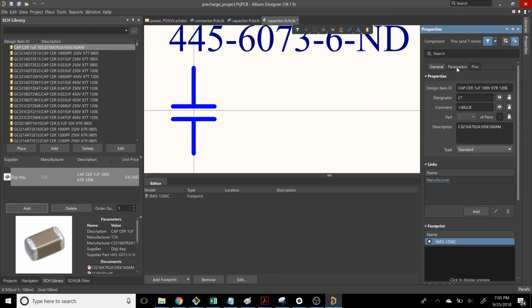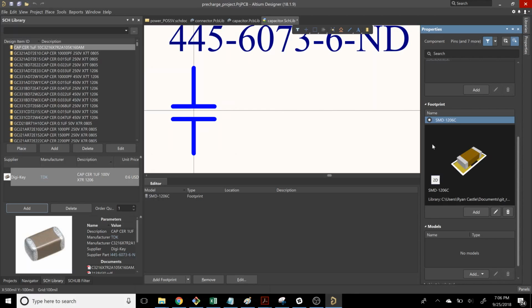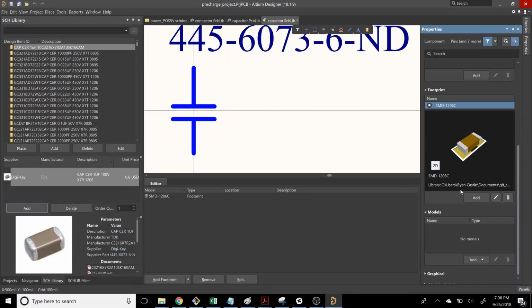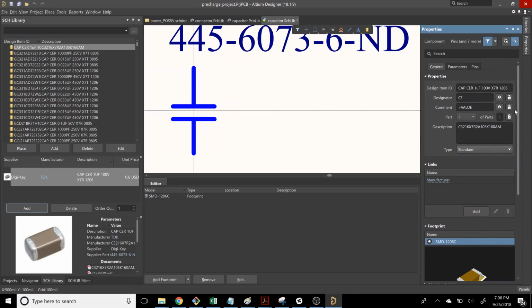If you go back to the top of this window, if you look at the footprint, you can see the component footprints that's in there. So you can just tell that those are linked. And then for a model like this, the 3D is incorporated into the 2D footprint. But sometimes if you do your own step model, you might need to add in a separate footprint or a separate 3D component and get that connected in.